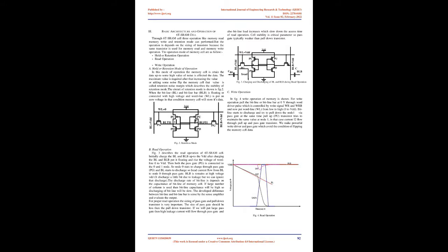As we are increasing the number of transistors on the system on chip, SoC, power dissipation is considerable in both active as well as standby mode. So to reduce the leakage we need to reduce the supply voltage, as we discussed above. For standby mode or hold mode we need to reduce the leakage of the memory cell by reducing the supply voltage of the system on chip, SoC, in standby mode.